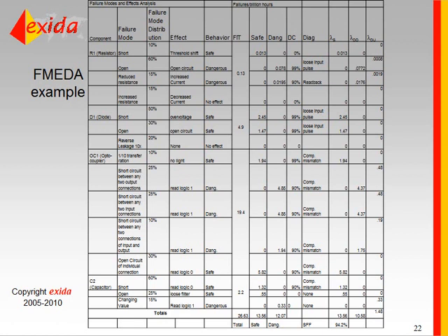And then to calculate the safe failure fraction, it's essentially the safe failures, which is the safe and the dangerous detected, divided by the overall safe and dangerous failures. So it essentially would be 13.56 plus 10.58 divided by 13.56 plus 10.58 plus 1.48, which comes out to 94.2% in the case of this product.